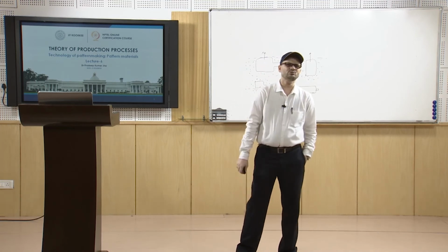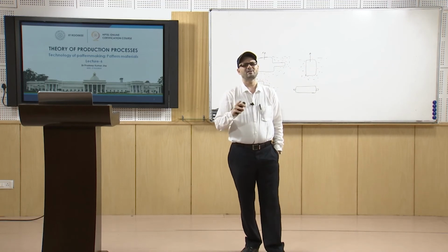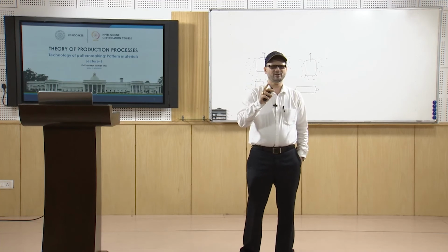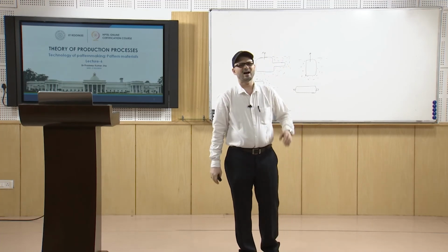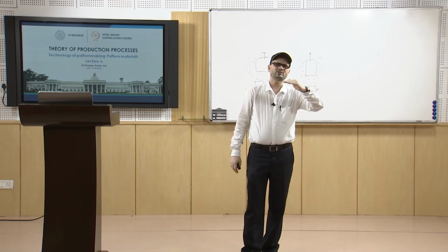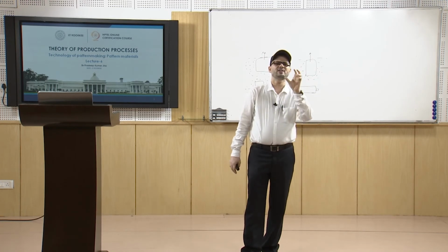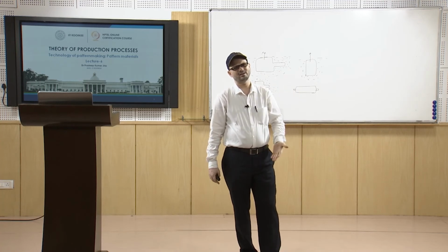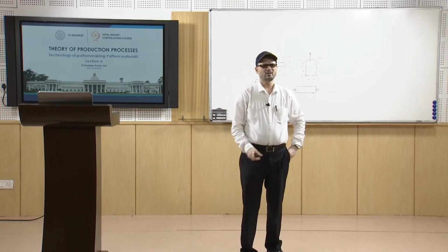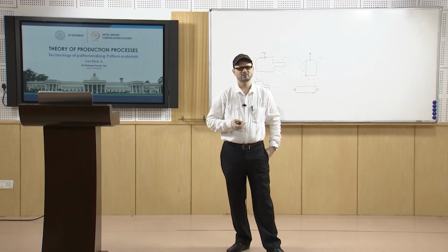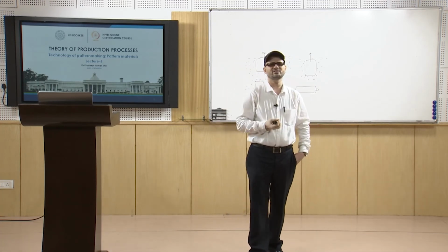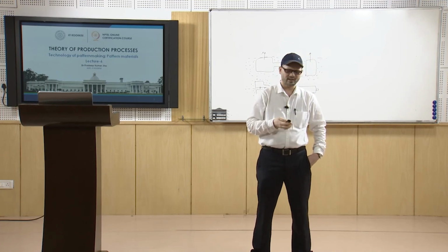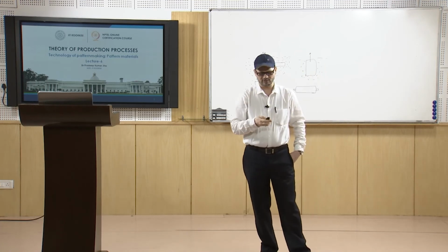The factors which you must consider are availability, castability, machinability, surface finish, weight, brittleness, and cost. All these factors are important, because when you take any material, it should be easily available. If you have to further make it, it should not be the case that it is not available and you are going for another material. It should also be easily castable, so that you are casting the material and getting it in a certain shape. Then machinability, surface finish and all these properties should be there.